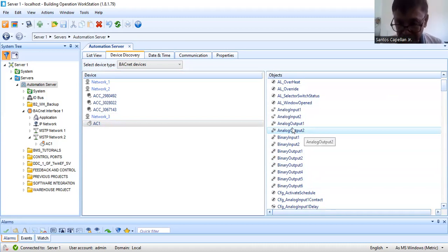Now, actually, if it is a solenoid valve, it will be an open and closed control. Okay, it is not modulating. A solenoid valve is just like a relay. If you remember the relay, if you give a supply to the coil, then that valve will open. If you remove the supply, the valve will close. It will depend on the valve, whether it is normally closed or normally open. So you just make sure which the valve is, normally closed or normally open. That is also a point that you need to check.